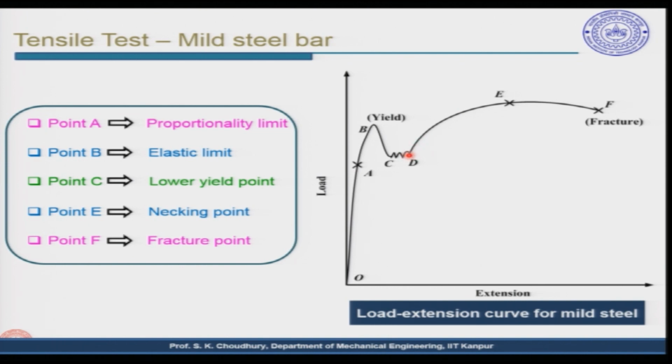All right. So, from D to E the strain hardening occurs, and the point E is called the necking point. I am explaining later what the necking point is, and then after the necking point is crossed, anywhere between E and F the material can get fractured. Material can get fractured, meaning that in terms of machining we can understand the chip is getting removed from the body of the workpiece.